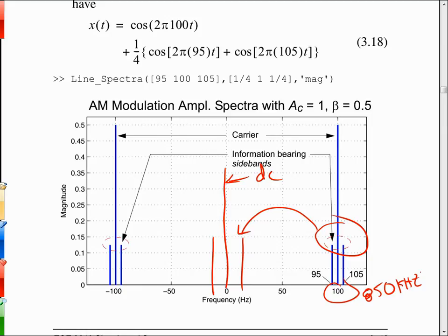What happens is if you don't have your cable system properly shielded and screwed into everything tightly, your cable will leak RF energy, and that energy can be picked up by that antenna on that cable truck, so they use that to see if you're leaking signal, because the Federal Communications Commission says, yes, you can have a closed-circuit network and rebroadcast signals on these cable frequencies, but we have other users, namely aircraft bands and other public service bands that are licensed for free airspace use, and if your cable leaks and causes interference, that's a violation.